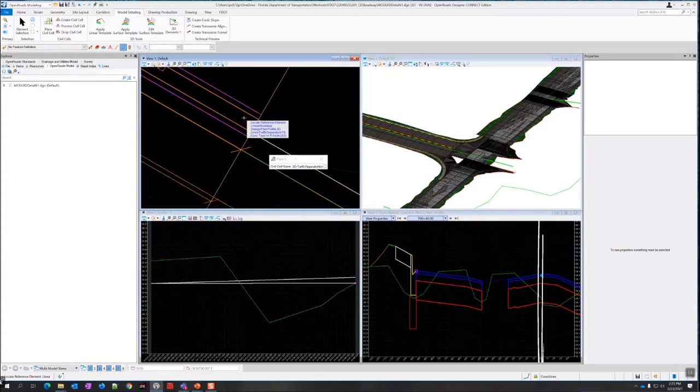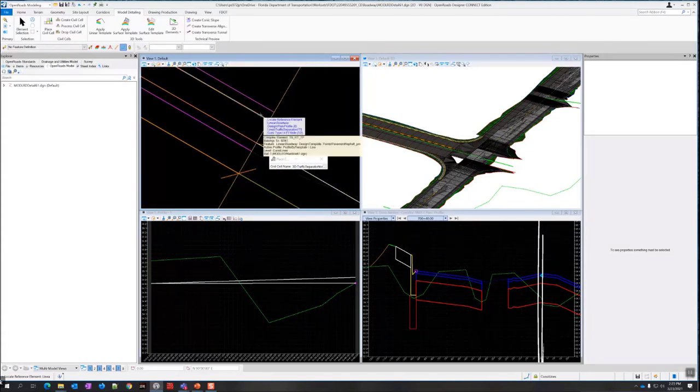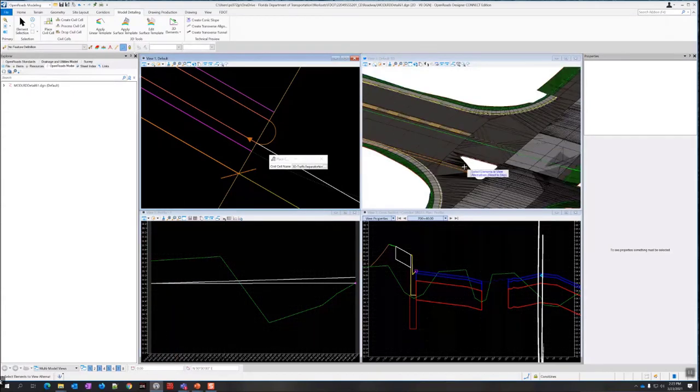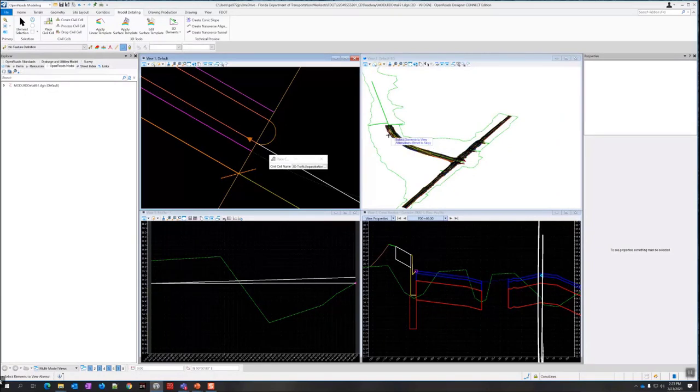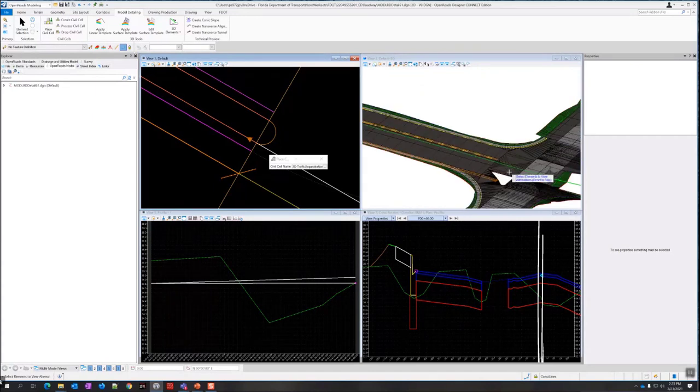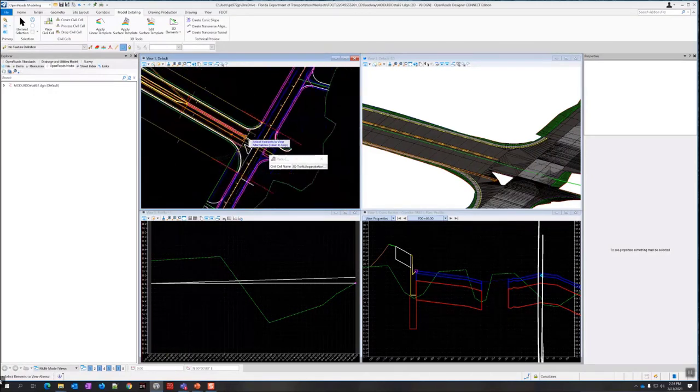It wants a reference element, so I'm just going to pick, you should be able to use the pavement asphalt PM lines. So I'm going to pick that. And then it's the same pavement asphalt PM on this side. So I don't like the way this is showing up. Does not look very promising. But the one thing you can do is cycle through the alternatives. Basically you click on these arrows, change the direction of the arrows for each line until it's looking right.